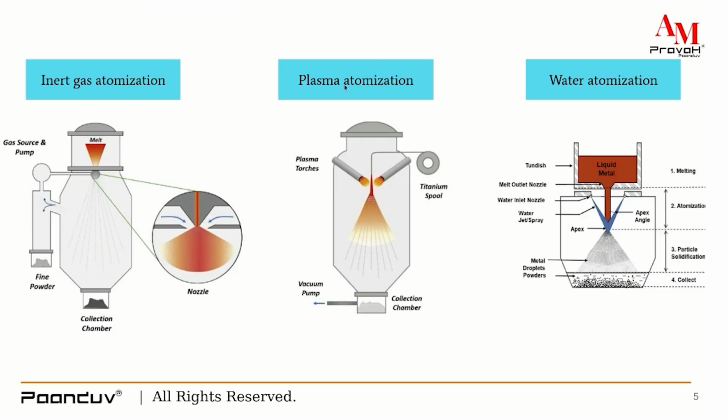The second part is plasma atomization, where you have these plasma torches which are coming in direct contact of the metal wire. The temperature over here reaches around 10,000 Kelvin and more, and this high energy process helps atomize the particles, and the atomization happens during the flight of these particles, and we get more spherical particles from these processes.